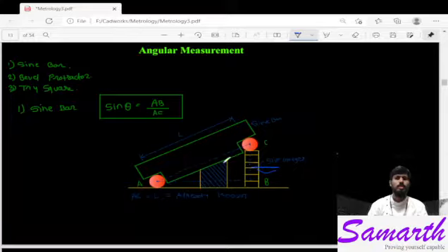Now our task is to find the inclination of this machine component or any component. By using Pythagoras theorem, we will find this inclination, as the height of the slip gauges will be known to us because we ourselves will be arranging these slip gauges one over each other.